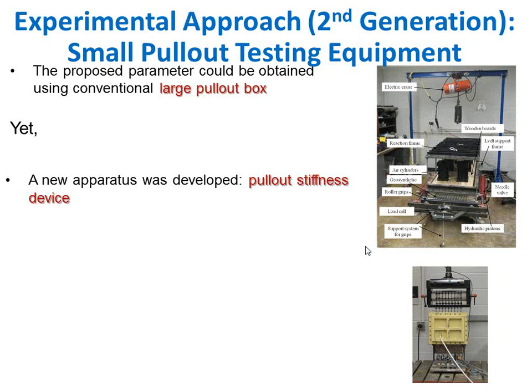But this is under confinement, so we apply confinement with air pressure, with the bladder. It's confined under the confinement of soil. And we measure the displacements within the reinforcement. Actually, we measure five different points.